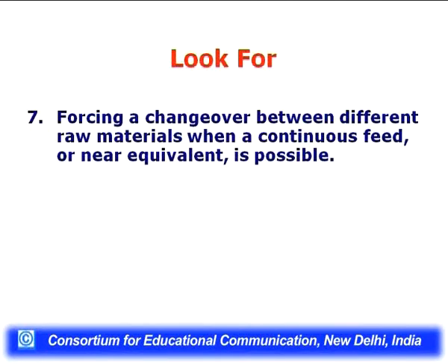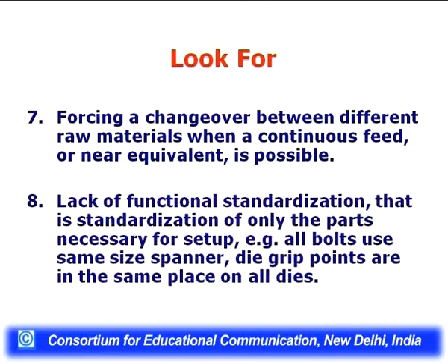Now, forcing a changeover between different raw materials when a continuous feed or near equipment is possible. Lack of functional standardization, that is standardization of only the parts necessary for setup, that is all bolts use the same size spanner, die grip points are in the same place on all dies. These are small things, and these are vital operations, and they reduce the time drastically.